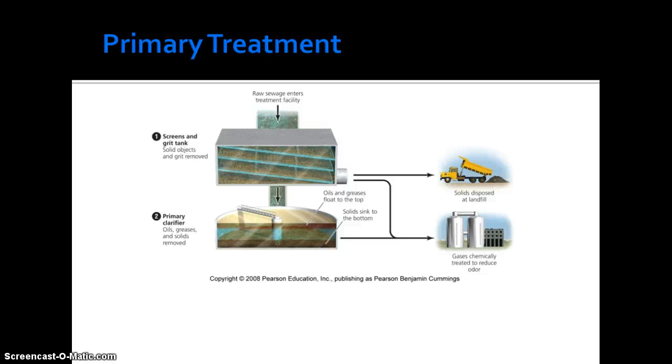the water column. Materials less dense than the water will float to the top and can be skimmed off, whereas heavier sludge can be collected from the bottom. Any large debris can be dried and disposed of in a landfill or through land application. The clarified water then flows to the secondary treatment phase.